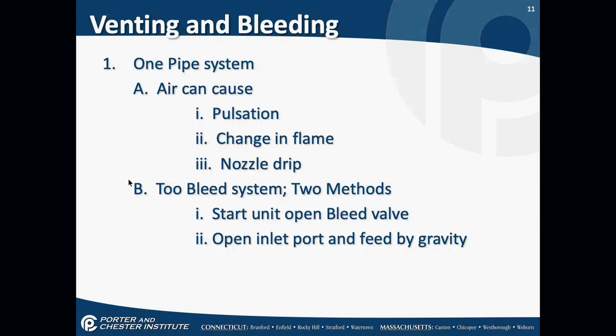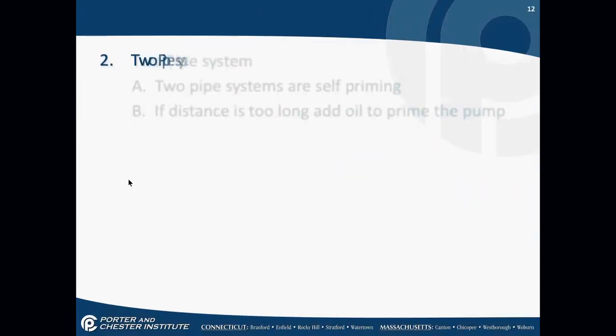On every oil pump, and I'll show you a picture eventually, there's a little bleed valve. You start the unit, you open the bleed valve, and you feed it by gravity. The bleed valve shoots oil out of it, so perhaps you want to put something under it to capture that oil, because the homeowners hate oil on their floors.